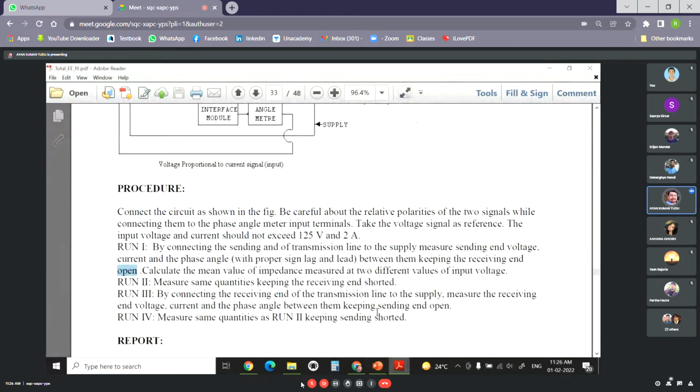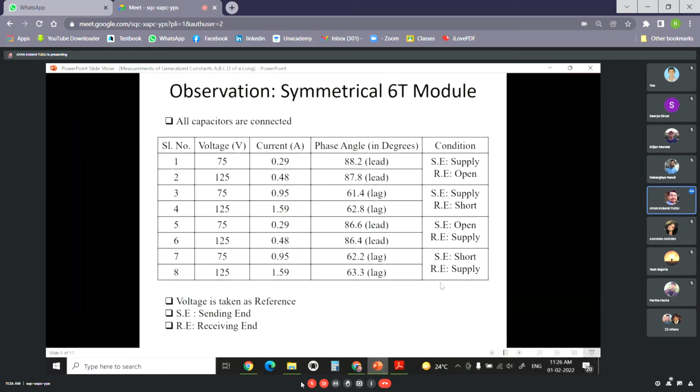I think I have misplaced it, but whatever be the case, whenever we have a Ferranti effect, we have a shunt inductor. It will draw the excess reactive var from the system, so that the voltage at the receiving end goes to its nominal value. In that way we can control the voltage at the receiving end side.